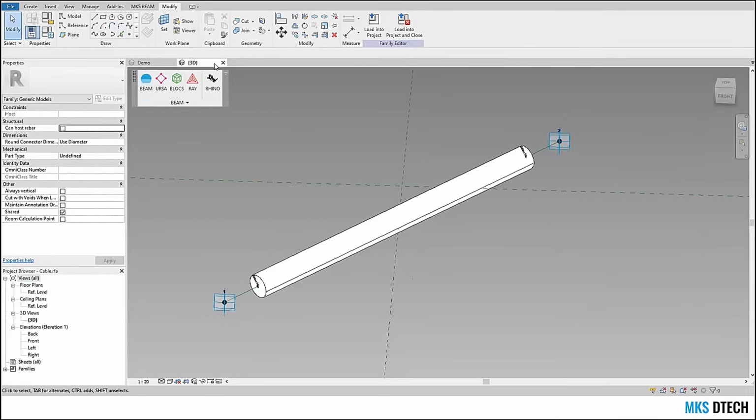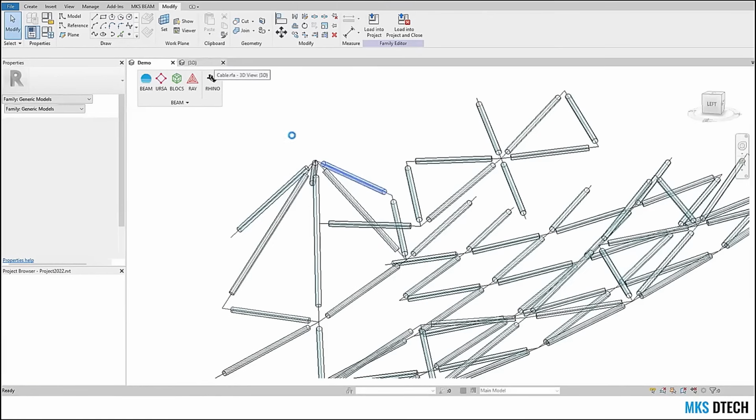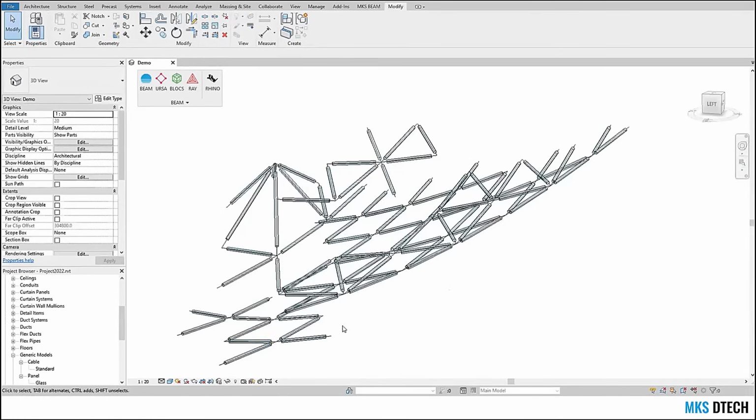Yes. If you want to place native connectors, you can still export the curves and open them with Dynamo, and there are many other nodes to create those kinds of beams and columns using lines and NURBS curves. So you can do the export and then just use Dynamo to feed the other parameters that are needed to generate those kinds of components. Yeah, exactly.